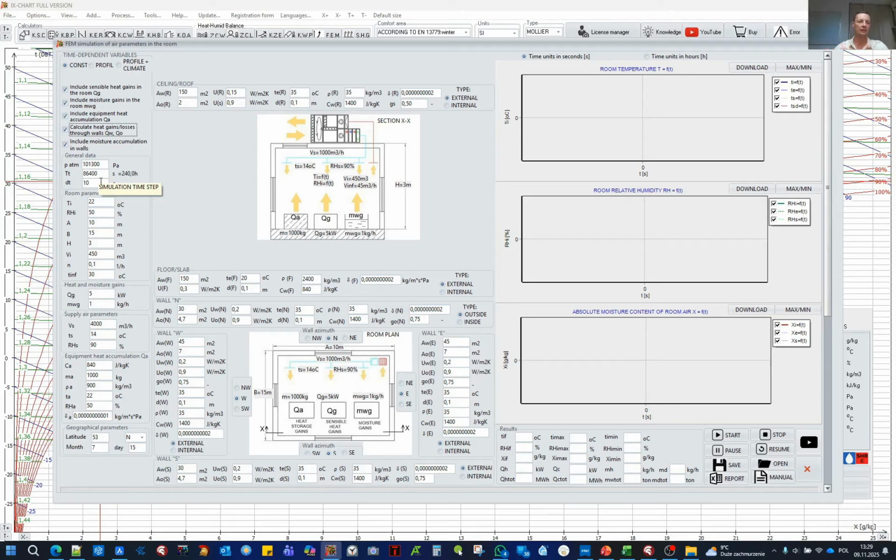In connection with the above, it should be adjusted appropriately to the length of the entire simulation time. As a consolation, I will say that the program independently suggests how long this time step should be, depending on the duration of the simulation. And such a time step is selected automatically, although sometimes it happens that despite this, the simulation may go beyond some stability range. And then this time step needs to be manually reduced, which will of course be covered by an additional prompt from the program.